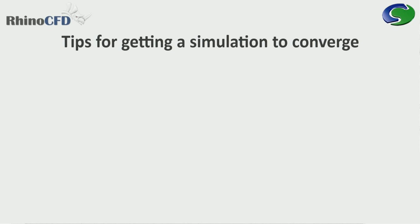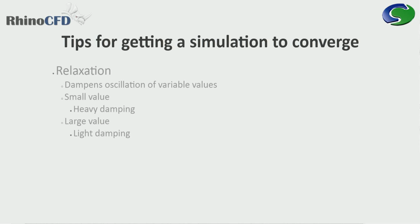To get any CFD simulation to converge, it is necessary to employ a technique known as relaxation. Relaxation essentially damps oscillation of variable values from iteration to iteration. It is akin to damping in control theory. Each variable has a relaxation parameter that can be set by the user, which controls the strength of the damping. Note that a small value for the parameter gives a heavy damping, and vice versa.